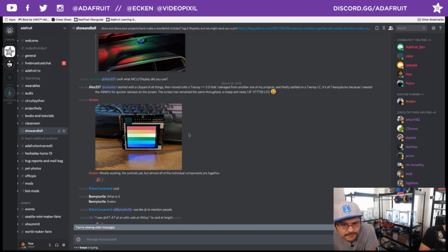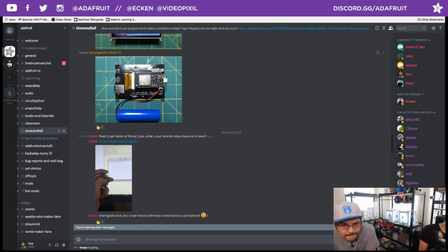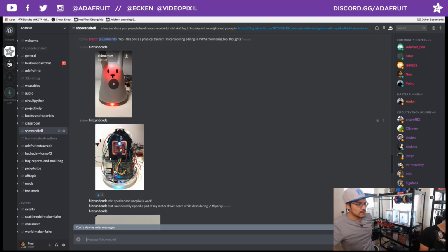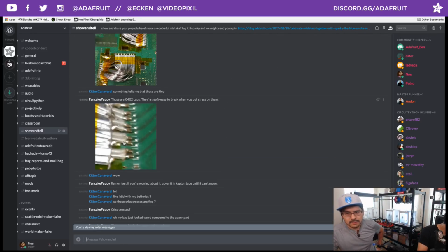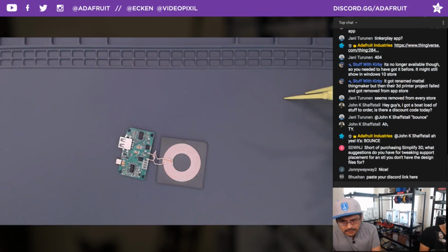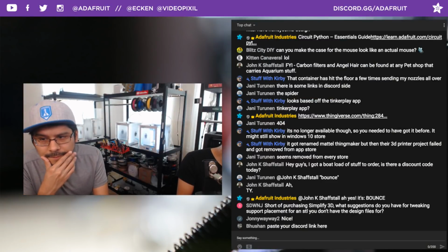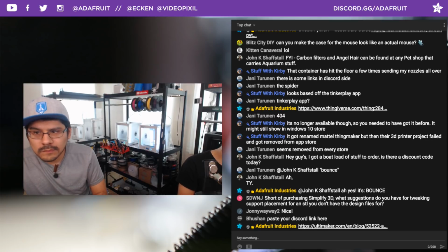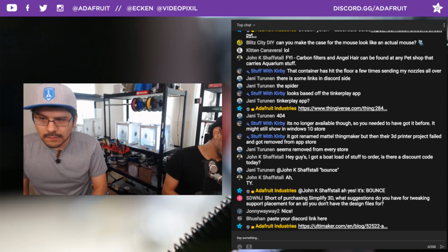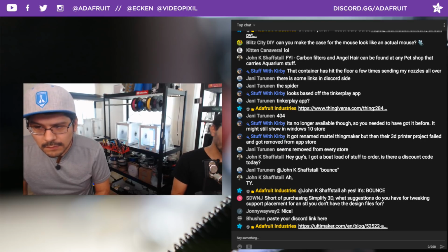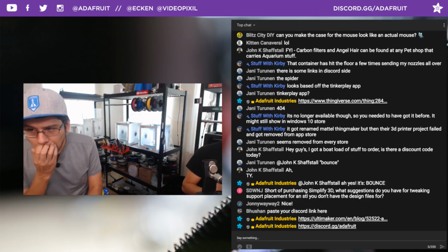Yeah, if you guys want to start posting any questions there, I just saw one from SWNJ asking, short of purchasing Simplify 3D, what suggestions do you have for tweaking support placement on STLs you don't have design files for? So the new version of Cura 3.3 beta, I posted a link right there for the blog post on that. One of the cool new features is they added a support blocker, which doesn't let you actually place supports where you want them, but you're actually able to block the supports that you don't want.